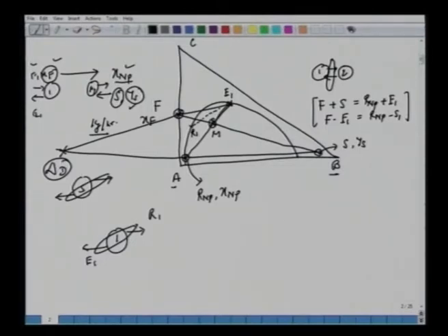The idea here is very similar to what we had in the case of a distillation column. We located del D and del W points because the difference between the molar flow rates of the two streams arriving and leaving is constant and equal to the top product or the bottom product molar flow rate. We have a similar approach here, realizing that the difference between the raffinate and extract, at stage 1 or stage 2 or stage S, anywhere, is a constant difference, so we locate this difference point. Once we know the difference points, we can have the operating line and the tie lines, and we can proceed.